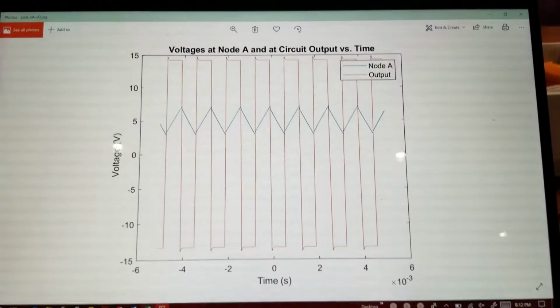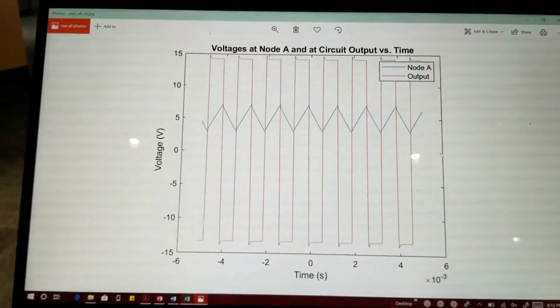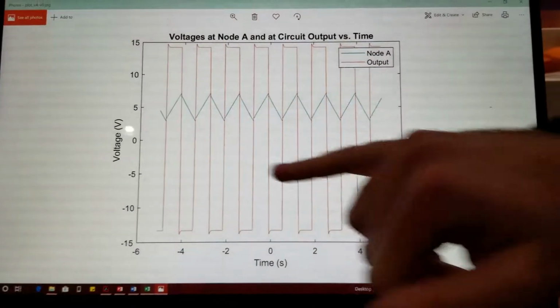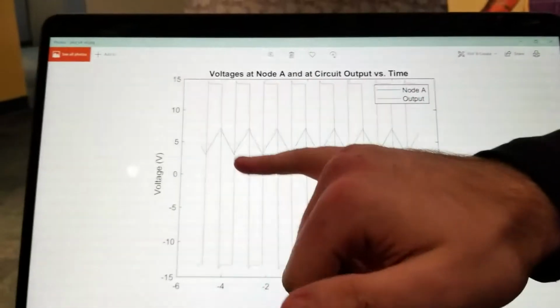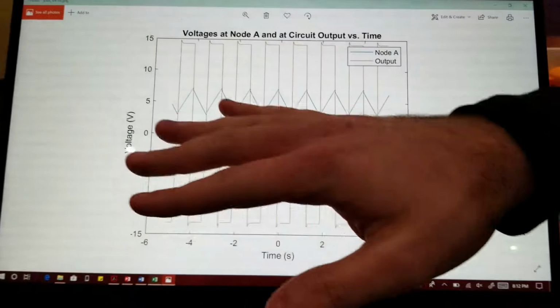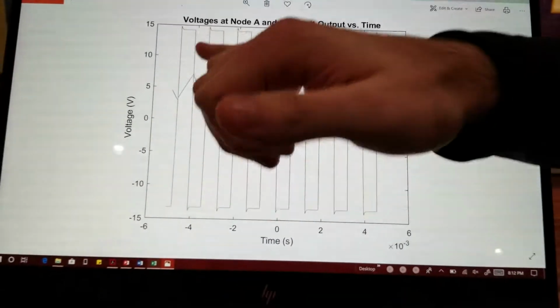so we have a high output state as you're going from low to high voltages, such as in this part where the troughs and peaks of this waveform correspond to the rail voltages, to the threshold voltages that the VCO is designed with of 3 and 7 volts.